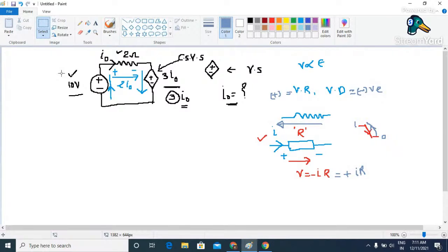So once you are done with this, let me erase this so that we can solve this numerical, or let it be as it is. We have enough space to solve this numerical. Now see here. In this circuit, suppose I am moving in a clockwise direction, like this. So first I need to pass through this particular element, which is a voltage source. I'm moving in a clockwise direction, that is from negative to positive. So I'm going to experience a voltage rise, because I'm moving from lower level to higher level.